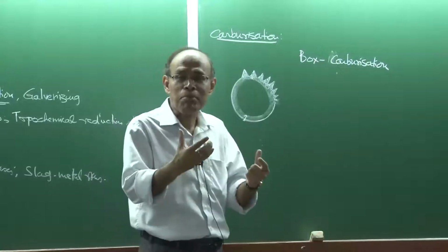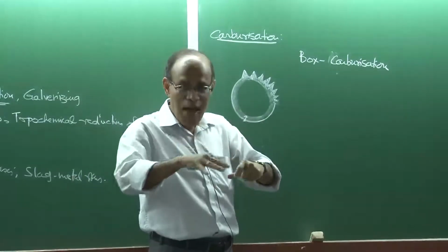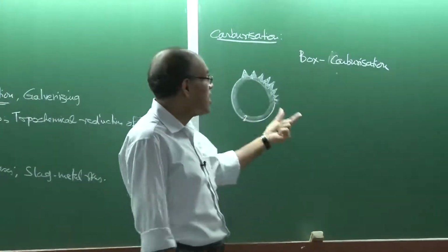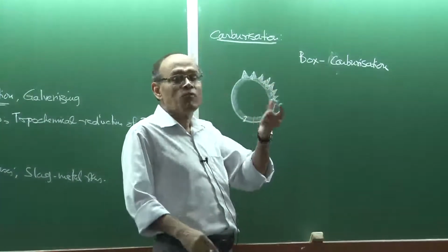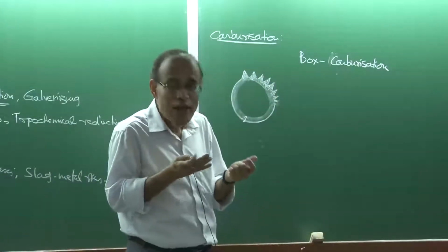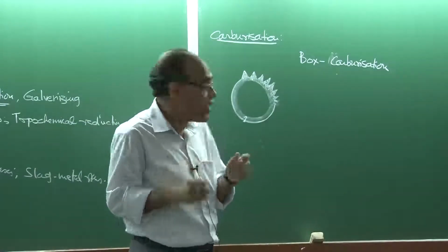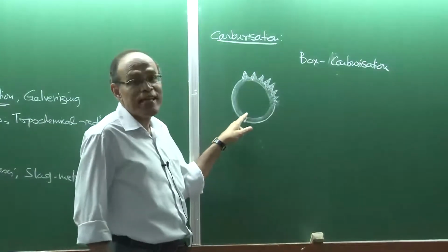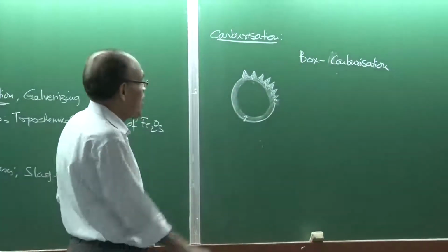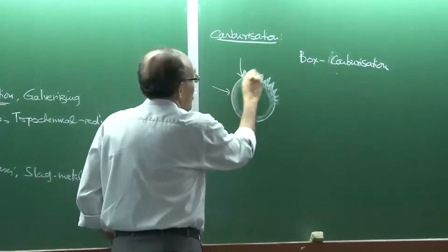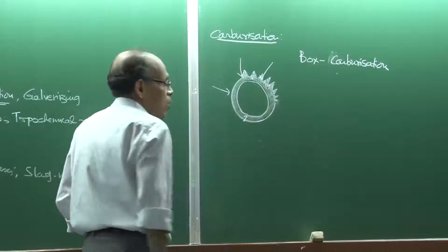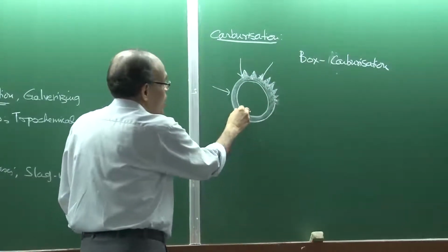So you take a steel sample, put it in a box, and pack it with carbonaceous material, and then you heat it for some time, 1 hour, 2 hours, and then you take out the sample, cut it, and look under the microscope to see what region you are getting. So you could see this boundary very nicely. Okay? And there, because carbon will be diffusing from all sides, the topochemical characteristics, that is the reaction front, or the penetration depth in this particular case, will be